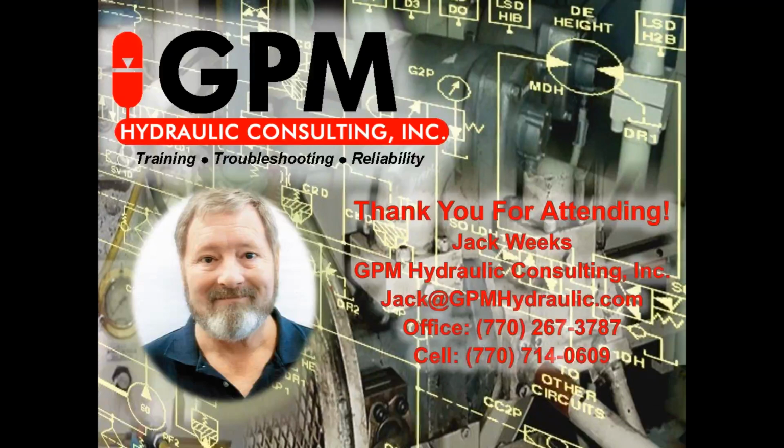To understand that, you need to understand what cavitation is. A lot of people confuse cavitation with aeration. But cavitation is a very steady, high-pitched whining sound. And it's caused by the pump trying to deliver more oil than it can get in. The pump is what we call a positive displacement device. It's going to make an attempt to deliver a specific amount of flow every time the shaft is turned. And that, of course, presupposes that you can get that much oil into the pump.